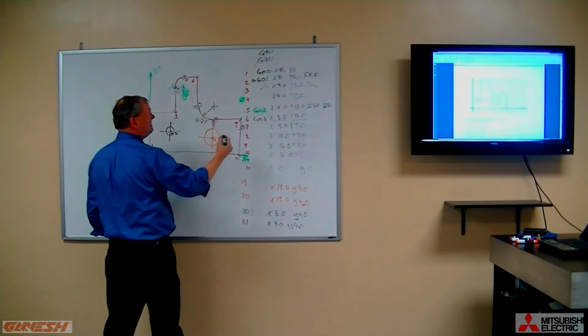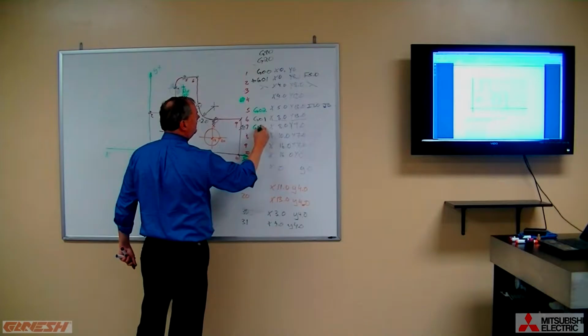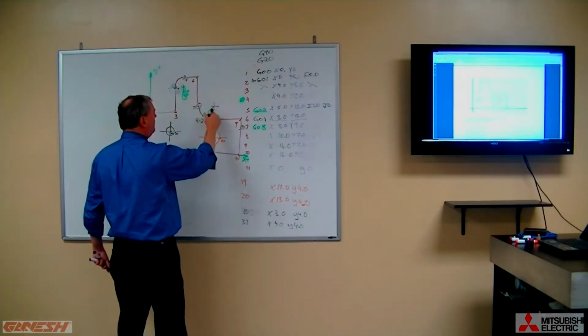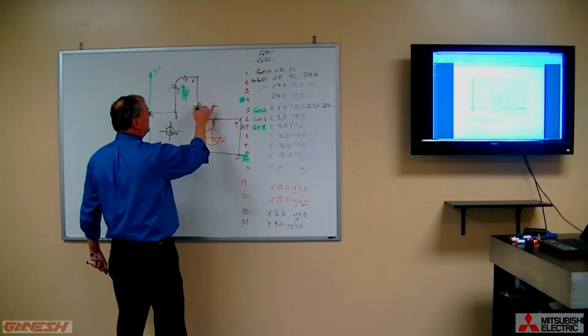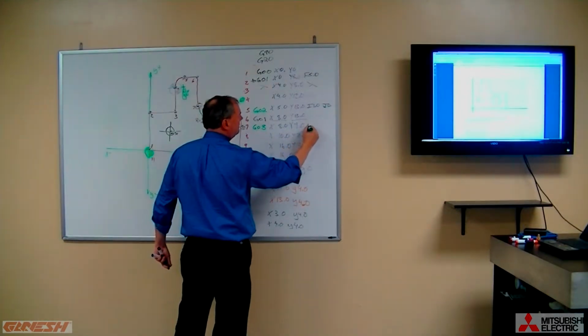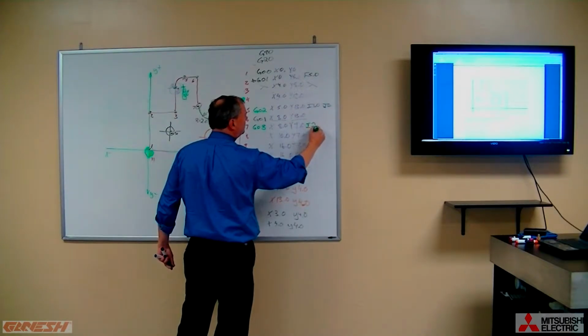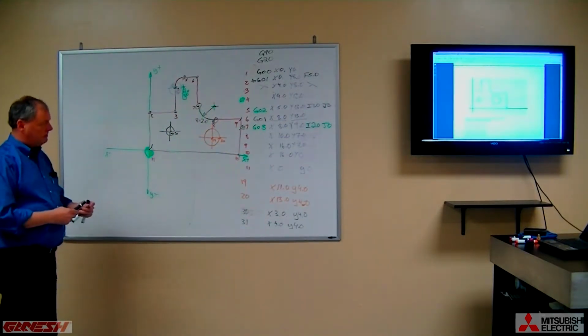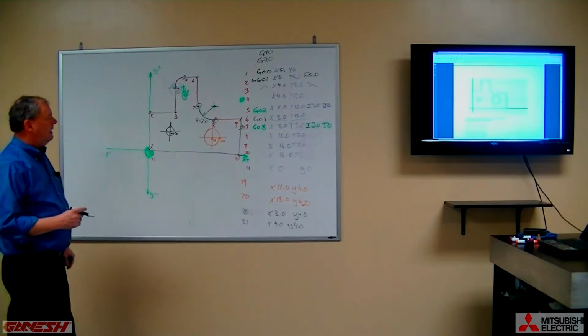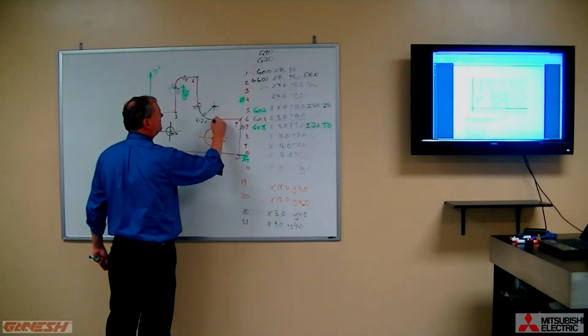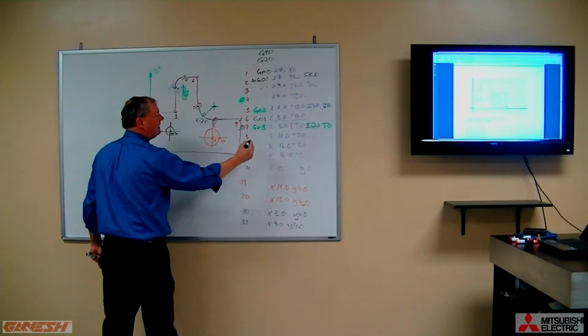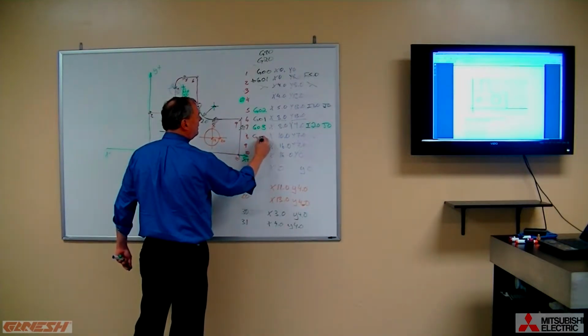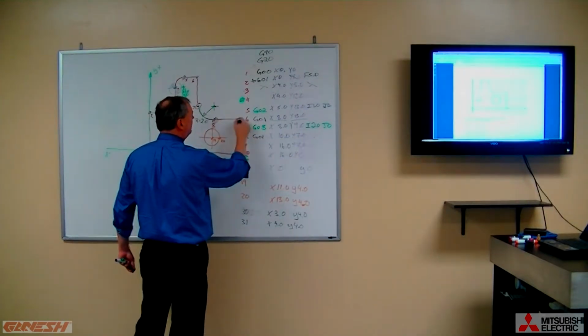It's counterclockwise. So I say G03. And now we're moving around the arc, and our X is our X value for the arc relative location. We substitute and say I, and then it's 2 inches over, and it's at J0. So now we have another proper arc command. Cutter's sitting here. We want to go back into a straight line move, so now we say G01 again, X10, Y7.